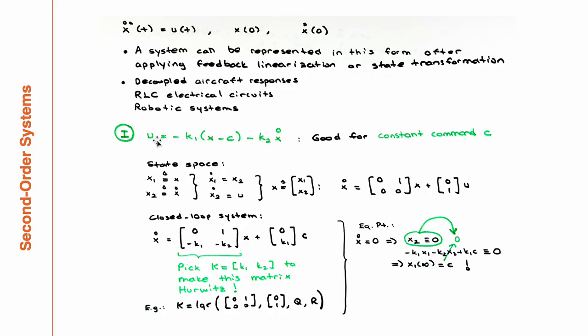First of all, when you have a system like this, I would like to go to state space to analyze. We did several examples of how we can go from differential equations to state spaces. Once again, if you had a hard time finding those videos, let me know. So, assuming you know how to go from ODEs to state space representations, just call x1 as the x, x2 as the x dot.